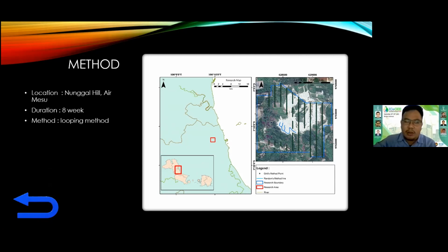And in this research, geomagnetic data acquisition is conducted using the looping method. The looping method uses a mobile proton precession magnetometer, or PPM. In this method, it is done in a base-to-base manner, which means acquisition starts from point 0, then ends at the same point at the end of the acquisition time. As you can see on the screen, there are green lines, which are various dots that represent the acquisition locations.